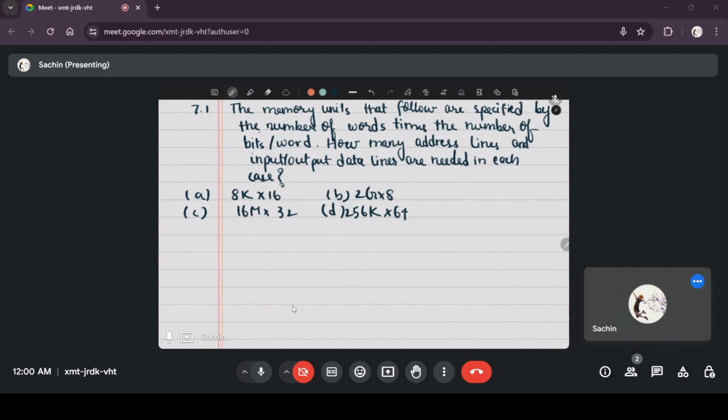You can select an address location by giving a binary input combination instead of selecting the line directly. What I mean to say is, if you have a few address locations, each with a different address, and a line pointing to each of those locations, then one way you could do this is to select this line directly and give 0 to all the other lines.